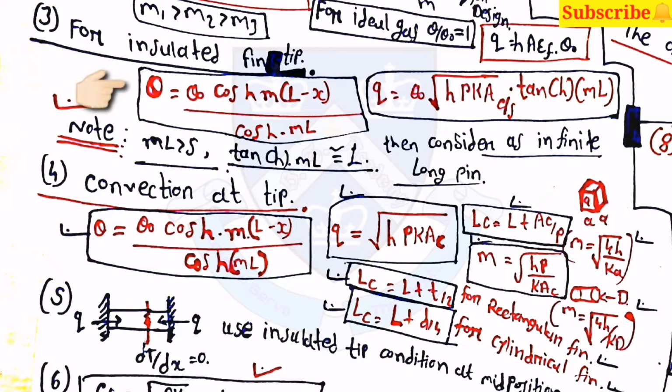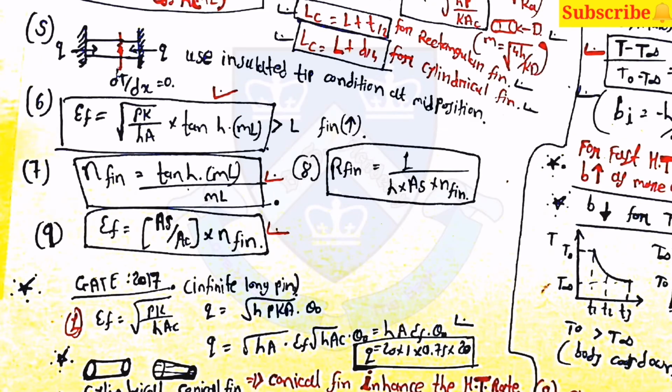Then the third one is for an insulated fin tip: theta is equal to theta naught into cosh m(L minus x) divided by cosh(mL). Similarly, the equation is given for convection at the tip. Here Lc is equal to L plus D by 2 for a rectangular fin, and Lc is equal to L plus D by 4 for a cylindrical fin. Then some more equations are there; you can take a screenshot for the efficiency and the effectiveness of the fin.